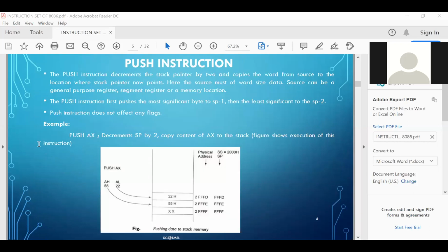the push instruction. Now push instructions are used to operate the stack memory location. Now, what is stack? Stack is a group of memory locations in RAM where you can store data bytes temporarily in structured form. Now if you want to store any data byte onto the stack, on some memory locations, those are used as your stack.